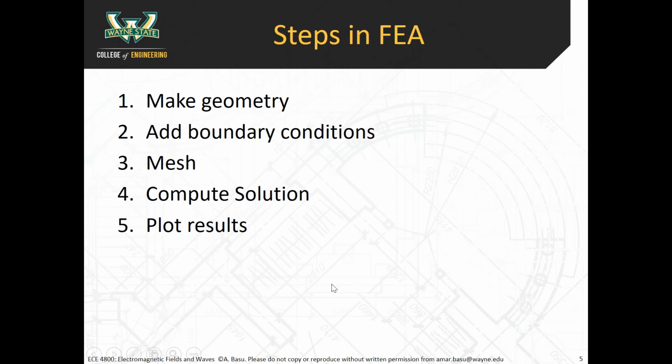The time-dependent solver also includes the continuity equation, but we're not going to be spending too much time on that today. So the steps in the finite element analysis, COMSOL being a type of finite element analysis solver, are to make a geometry, add the boundary conditions, mesh the model, compute the solution, and then plot the results. This probably won't take very long, maybe 20 to 30 minutes, and I'll show you how to do a finite element analysis within electrostatics using COMSOL.